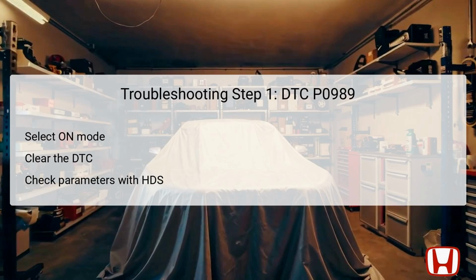The first step in troubleshooting DTC P0989 involves verifying the current statuses of various parameters using the Honda Diagnostic System, HDS. Start by pressing the engine start-stop button to select the on mode without starting the vehicle.